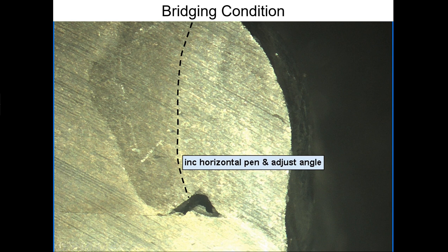If the aluminum doesn't stick to it, which it does not, you could take the oxide and knock it out of there like it's a chunk of stone, because to aluminum, that may as well be what it is. But in the condition you see here, that's not a good thing that I want to ship. I don't want to ship parts that look like this. We would take our die grinder, clean this area off a little bit, clean this area out, and then restore our weld to where it's supposed to be.